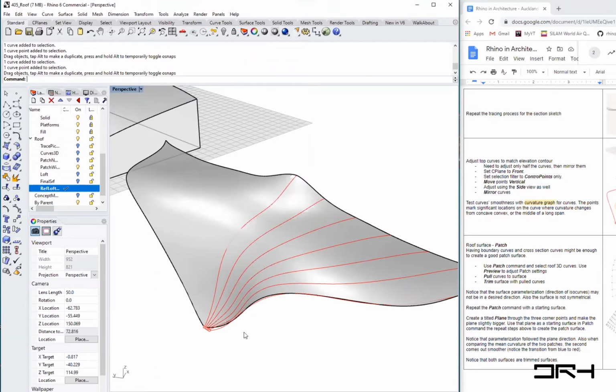Now I'll introduce a functionality here in Rhino, which is history. If you look down at the status bar here, there is record history. Right click on it. And it has the option to always record history. You don't want that. You just make sure you check update children, lock children, and history break warning. I'll explain how history works as we create the lofted surface here.